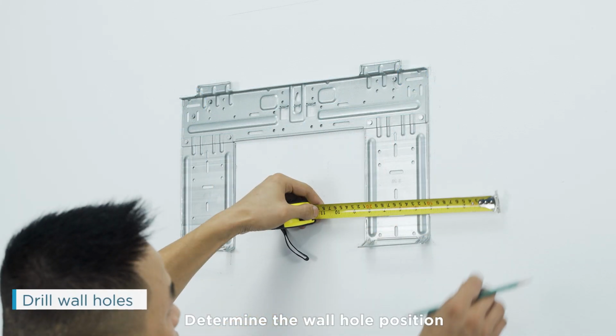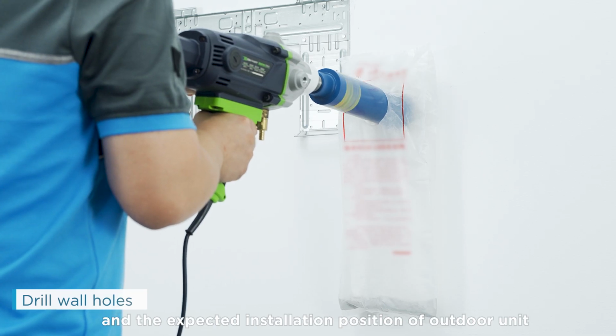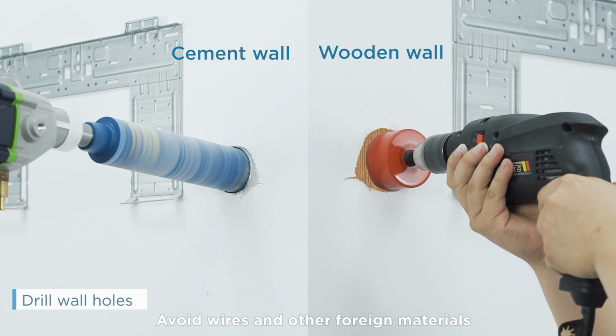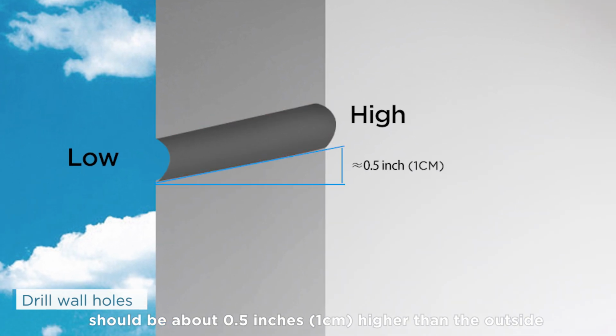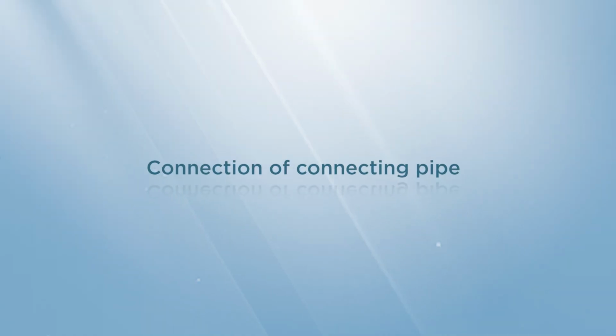Determine the wall hole position according to the exit pipe direction and the expected installation position of outdoor unit. Avoid wires and other foreign materials. Attention should be paid that the inside of hole should be about 0.5 inches (1 centimeter) higher than the outside. Put on wall socket. Connection of connecting pipe.